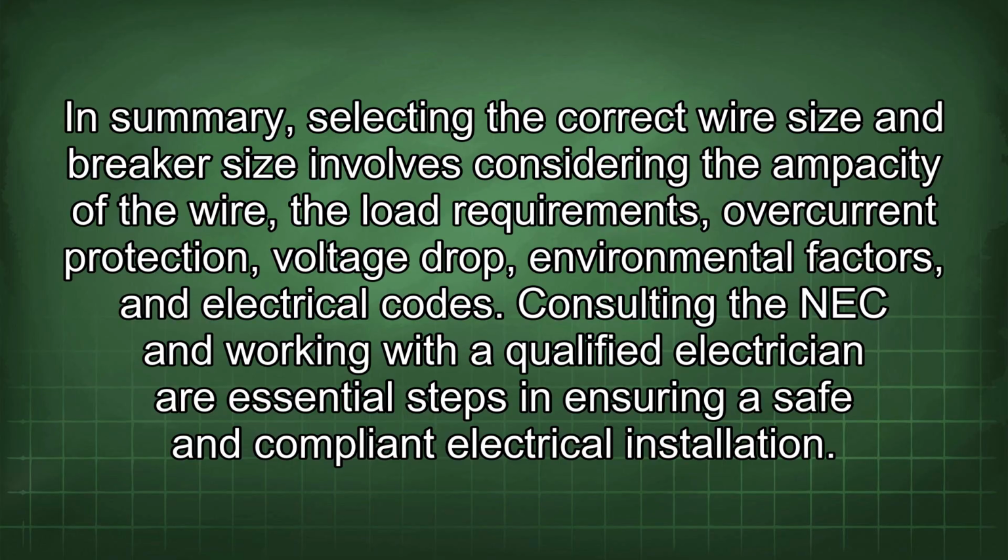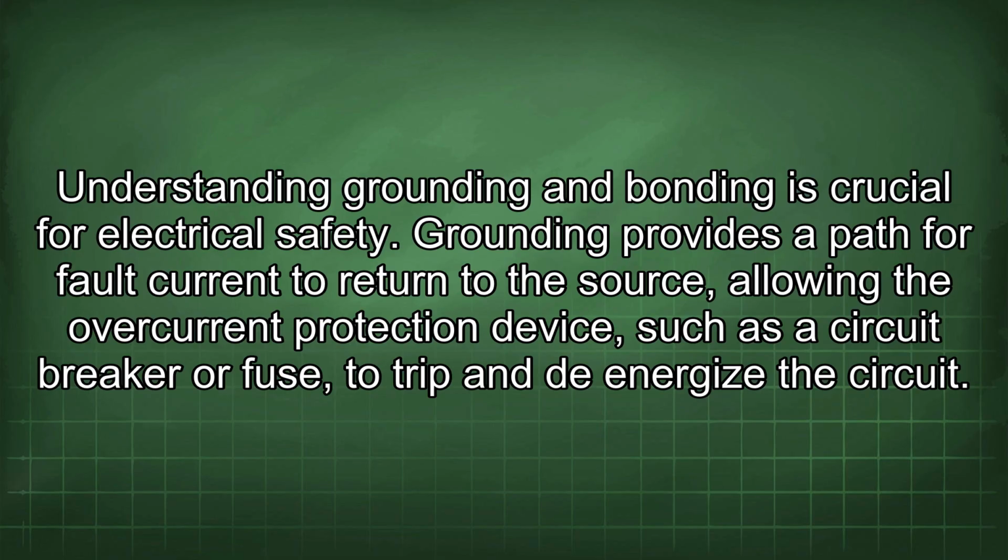Consulting the NEC and working with a qualified electrician are essential steps in ensuring a safe and compliant electrical installation. Understanding grounding and bonding is crucial for electrical safety. Grounding provides a path for fault current to return to the source, allowing the overcurrent protection device, such as a circuit breaker or fuse, to trip and de-energize the circuit.